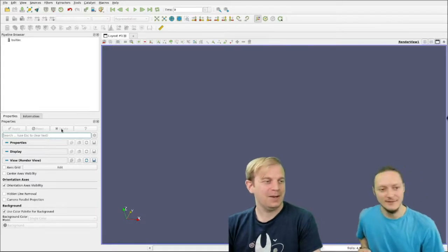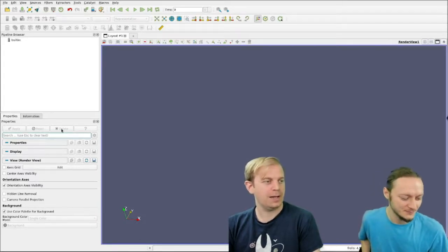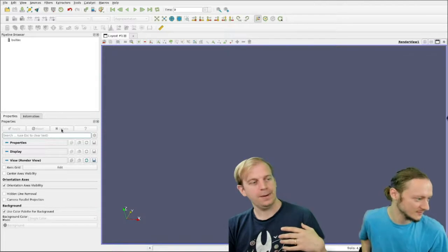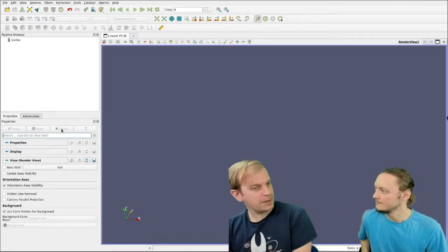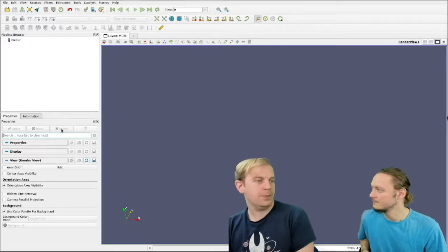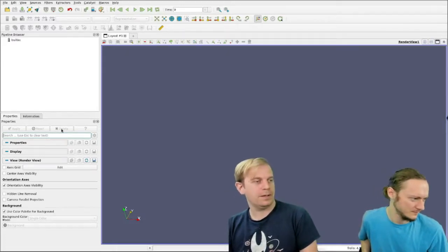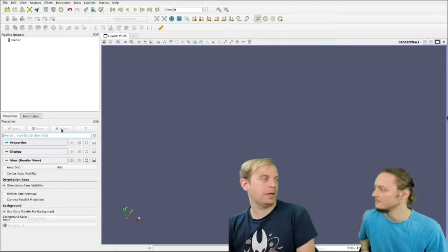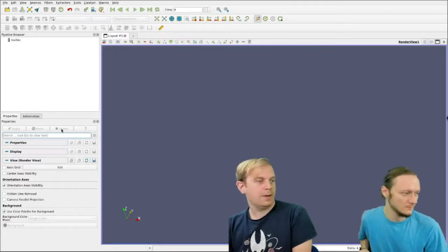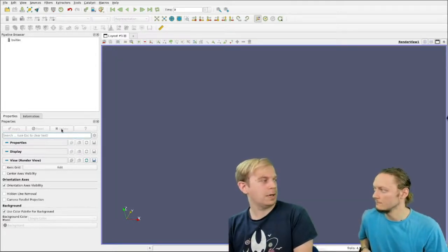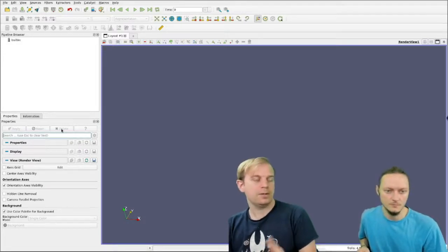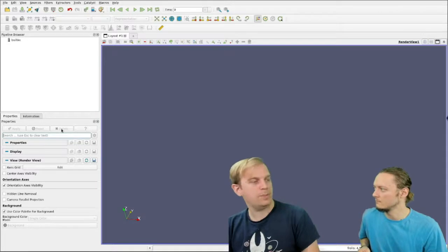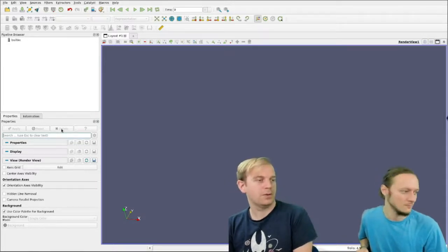But what you want to take a look into, Alex, is first try to use the stream tracer. The stream tracer does compute the vorticity, so maybe that's enough for you. And if not, you may want to take a look into the Lagrangian particle tracker. So search on Google for Lagrangian particle tracker. It's a plugin which is in ParaView. You can load it and use it. It's much more complex to use, but you can do anything you want with it. So you should take a look.